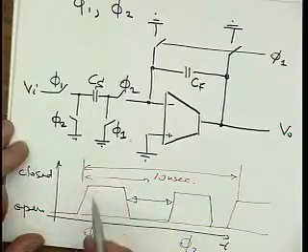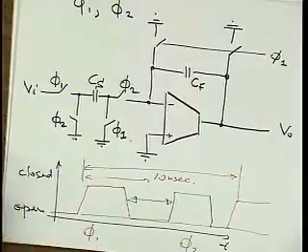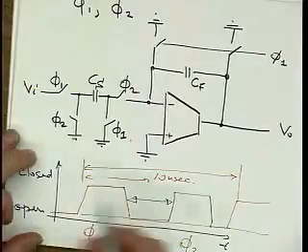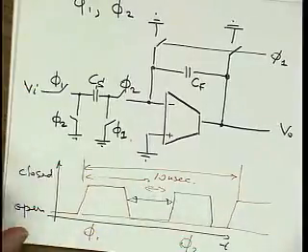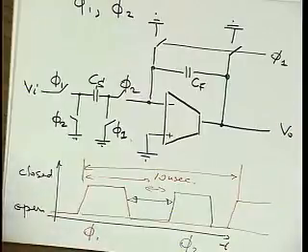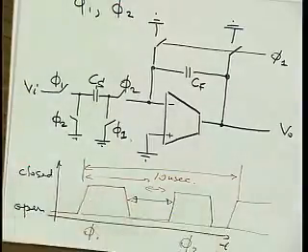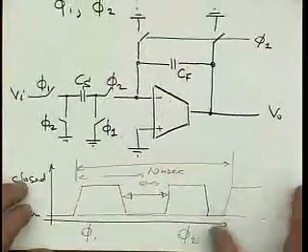Then for one phase, the best you can do is 5 nanoseconds, and from that you lose what's in the middle. So how much are you going to lose? Well, you're not going to lose nanoseconds, right? A few hundred picoseconds, that's what. And then of course the challenge is routing all the clock signals so that skew doesn't destroy the non-overlap, right? Okay, so